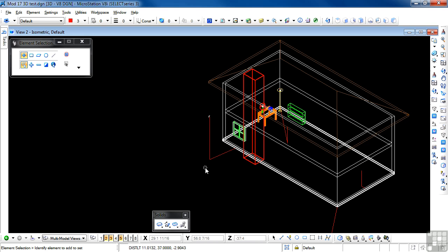An interesting exercise is to use volume effects, technically called volumetric lighting, to generate a scatter effect, similar to seeing dust particles in a cone of light. The effect can be applied to point, spot, directional, and solar lights. What I'm going to do, and I'd like you to work along with me, is to add 4 simple pot lights to the ceiling of our room and apply the volume effects to those.